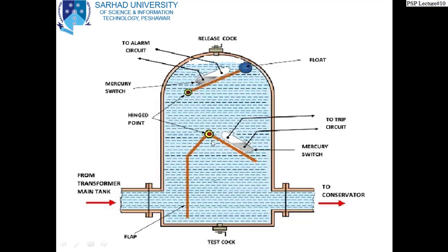Now, the transformer oil, when heat is produced, if we have an incipient fault, meaning an initially slow or low fault, it produces a heating effect. Due to the heating effect, the transformer oil, which is in the main tank, decomposes into its constituent elements. The two elements are common because it is an organic compound: carbon and hydrogen.